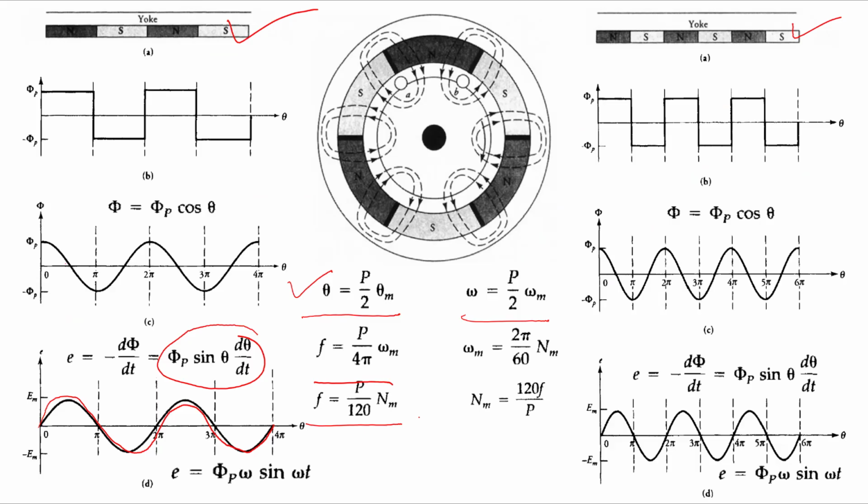So now we can see here that in case of DC generator, the armature was in the rotor and the field is on the stator. Now we'll just reverse it. We'll just say that the armature is on the stator, okay, and the field is on the rotor. So will there be any difference in EMF? In the waveform of EMF, will there be any difference? No difference, right? And we are considering here a single coil or single phase system, right?